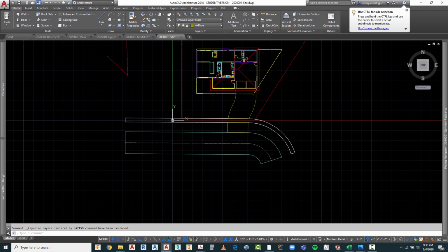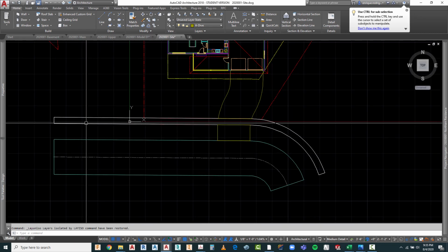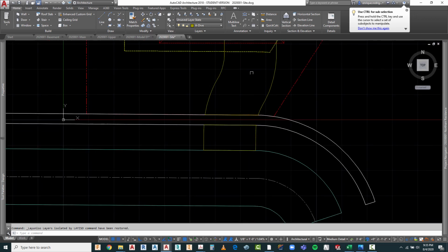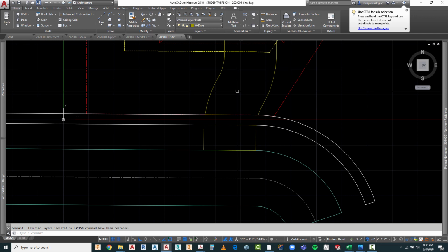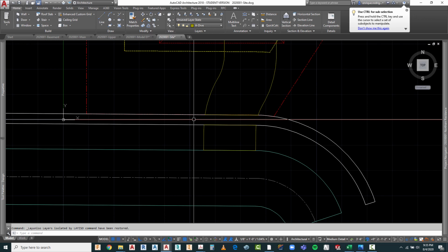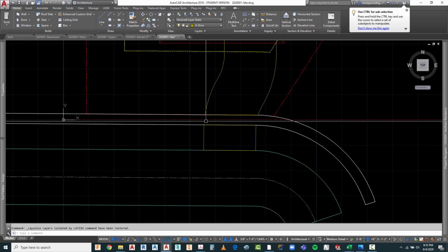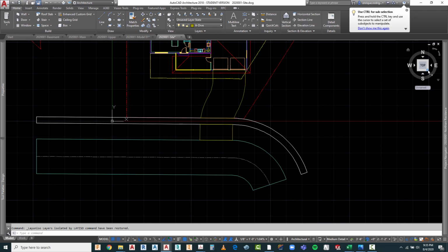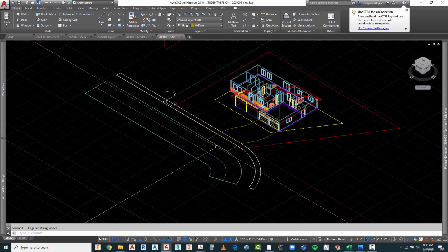I'm going to unisolate the layer. And the reason I've done that is because this sidewalk is what we would call a public right-of-way. And whatever material you have on your driveway, at least in this condition, is not going to be allowed to go over the sidewalk. Let's say you have cobblestone or something with a very rough surface, and someone walking along the sidewalk who's handicapped or blind then encounters a change in materials, and they unfortunately might have an accident. So that's part of the design features that we're going to do.